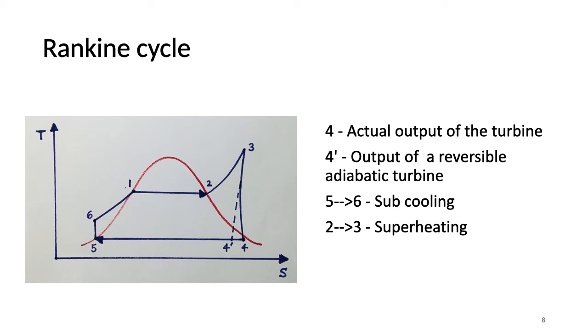In Rankine cycle, the vapor is superheated before entering the turbine to ensure that no water droplets are available. This is done usually with a separate superheater installed after the boiler. In Carnot cycle, fluid that enters the pump is saturated. In Rankine cycle, fluid is subcooled to avoid cavitation.